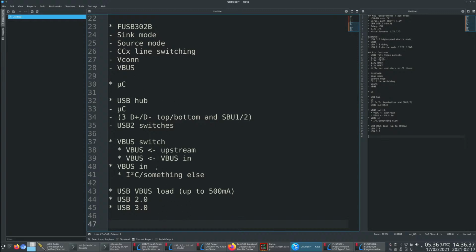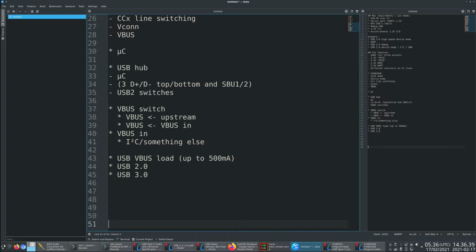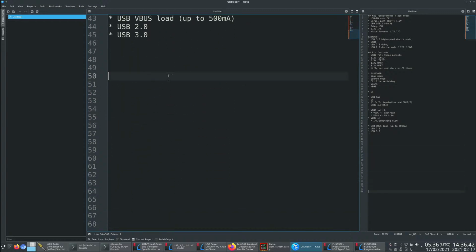So the architecture that we end up with here, and ideally I would draw a diagram, but I really don't want to start up Inkscape now, is we're going to have a USB host port that is going to have the USB 2.0 lines wired together, which is the standard for devices. It's going to have the USB 3.0 lines pass through to the target, maybe with jumpers, I'm not sure, or at least I'm probably going to put some kind of cuttable links on the PCB, so if this is going to be a problem, you can cut them.